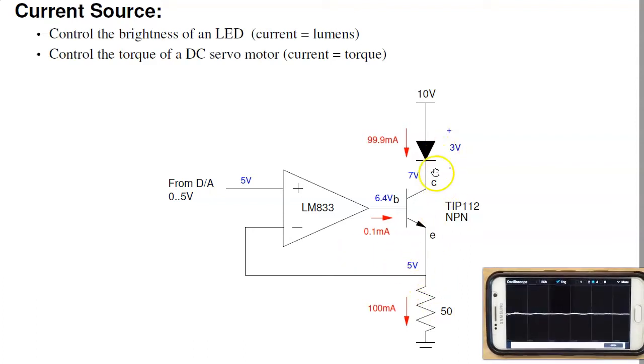I can specify the current through the LED very precisely with 4095 degrees of gray. And for an LED, current is brightness. If I replace the LED with a motor, for motors, current is torque. I'll have a constant torque motor. Eventually, if I apply constant torque, it'll speed up and eventually max out. Max out is I can't get more than 10 volts across the motor. So it will clip. But initially, it'll be a current control device.